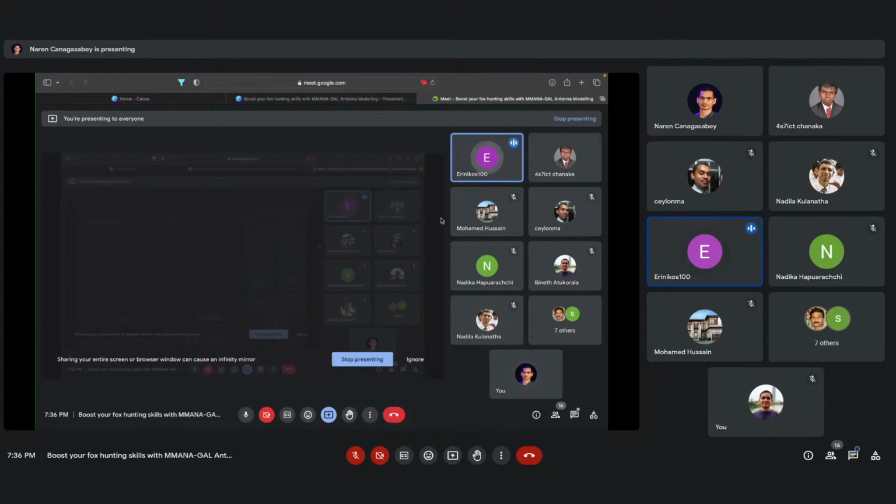You would have to go to wire edit and break up the elements into, say, 4 parts, 5 parts. I think the possibility is endless. So, say, break it up into 4 and then do the tapering. I think it'll get a little complicated if you were to demo it now, but to answer the question very briefly, it is possible to do by breaking the element.